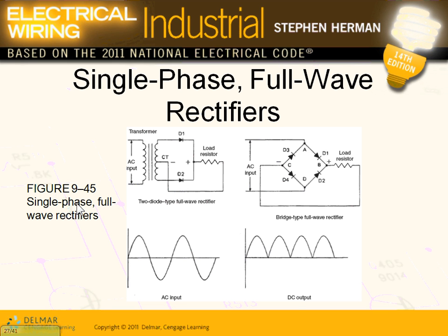The second way, guys, is full wave rectification, single phase. The best way to do it is what you're looking at right here, guys. We're rectifying AC to DC to dump it across a computer. All these machines are running DC. That's how they do them. So what they do is they put two diodes, where if the signal is positive, it charges one way. If it's negative, when the signal gets to the bottom, it flips the polarity and flips it to the other way. So it gives you some type of DC, it's not really a DC, but that's the whole idea.